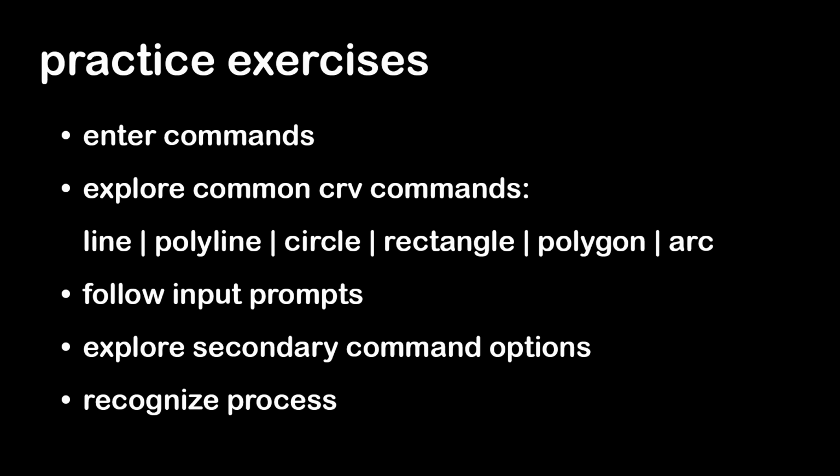As you practice, get comfortable with following the input prompts. Then try refining your control with the secondary options within each command's parentheses. Common curve commands are line, polyline, circle, rectangle, polygon, and arc. Take some time to really practice, as this process really lays the foundation for everything else moving forward.